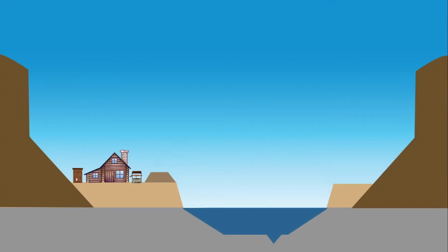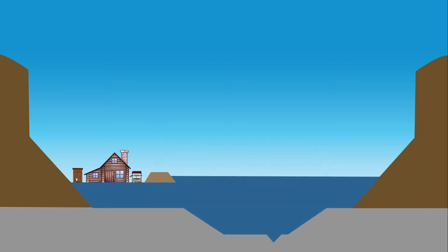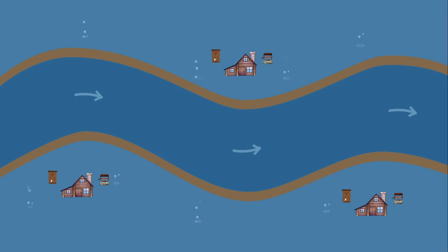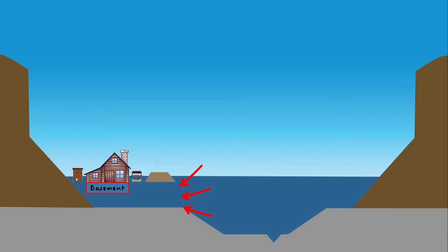In some areas of the valley, this sand on top of the clay next to the river is so porous that the water pours in here, and in some circumstances gets into the basements of the properties. In a few areas of the valley, it actually comes out of the ground once the flood has hit about 30 to 48 hours at the higher level. The higher we make these dikes, the more pressure is caused into this area, and it wants to equalize and come up, and that causes more out of the ground, but also forces it into the basement areas.